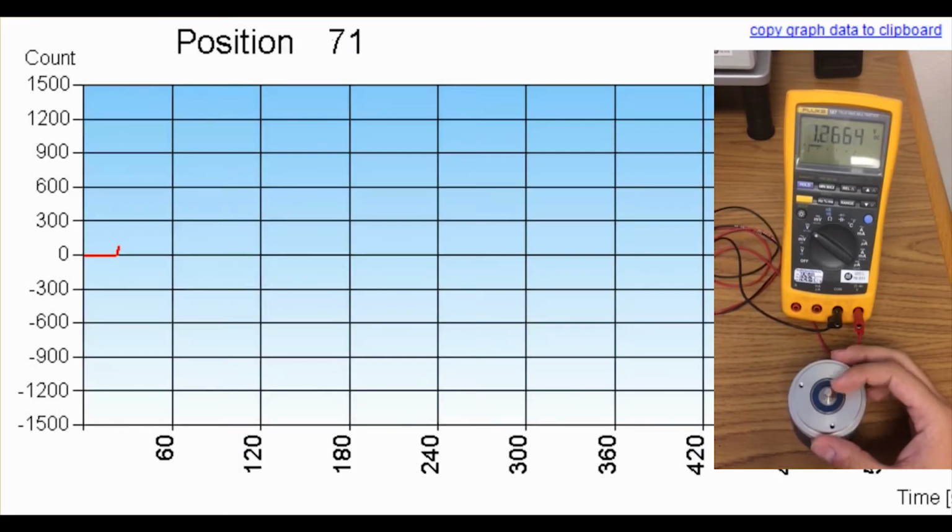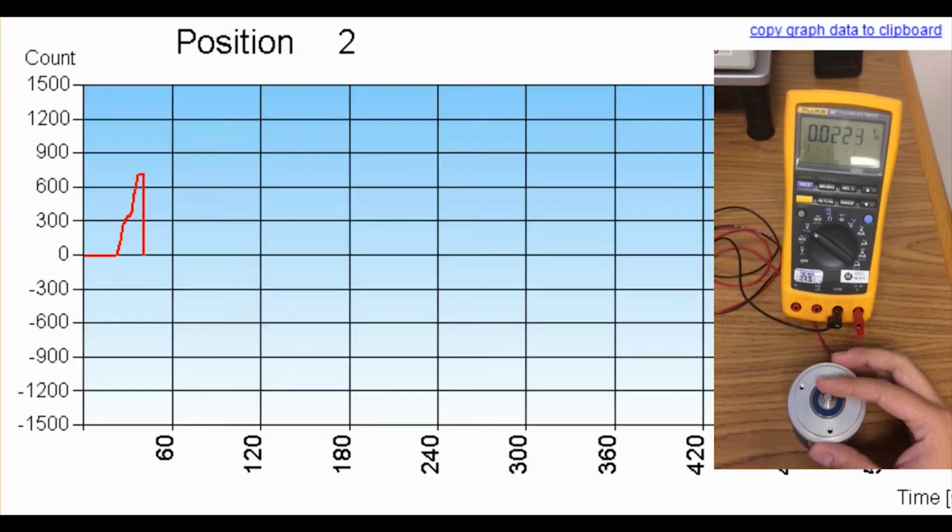Under the Operate tab, you can monitor a live update of the encoder. I have also gone ahead and set up a multimeter to show the analog voltage output of the controller. Notice that as I turn the encoder, the voltage output begins to ramp up from 0 volts. At one rotation, or a position of 360, the voltage is at the halfway point of 5 volts. After 2 full rotations, the voltage reaches 10 volts and then resets back to 0 volts.